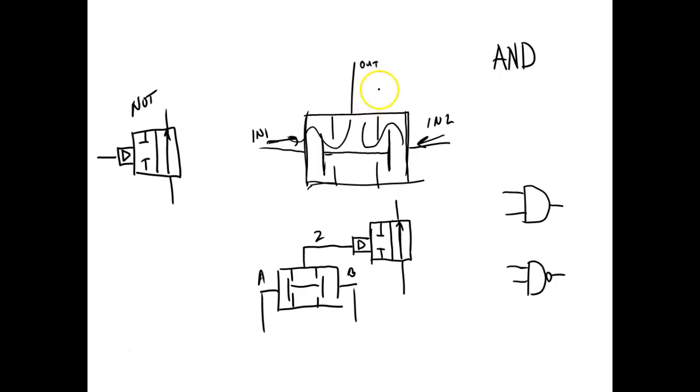That's a NOT. This is a what? That's an AND. So if I combine an AND, if I take the output of an AND and feed it into a NOT, I get a NAND. And then this right here is a shuttle valve. And this gives me a what? OR. So if I take the output of an OR, send it to control the NOT, then I get a NOR, right? You understand? If I take the output of the AND, let it control the shuttle valve,